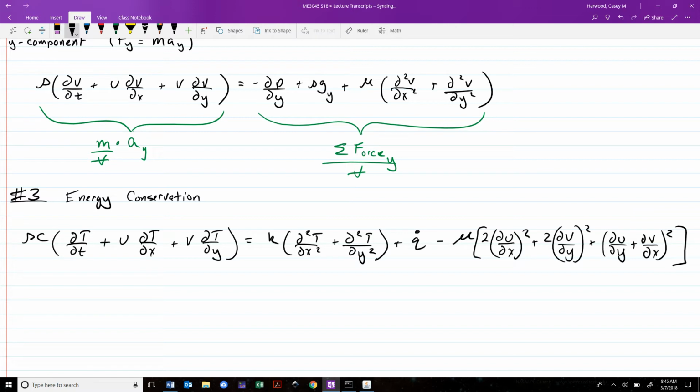All right, so this is the infamous energy equation. And this is one that we did not see in fluids. This is a new kid in town. But we should see some parts of this equation that are pretty familiar to us. So we've got our rho c, our capacitance, time rate of change. If we take rho c dT/dt, we should recognize this from our unsteady heat equation. It's just saying the rate of change of thermal energy per unit volume.